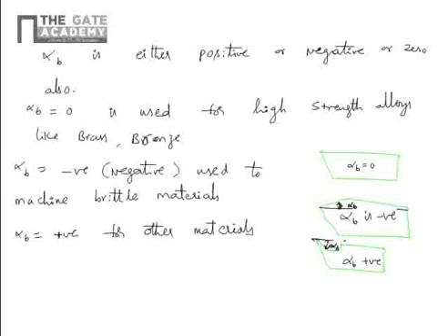Cutting force: with a decrease in the rake angle, the shear plane angle decreases, and for the same depth of cut the extent of the shear plane increases, and thereby the cutting force increases.